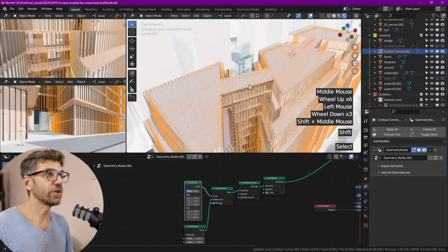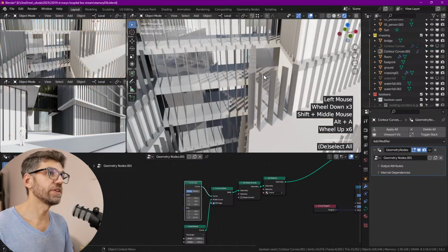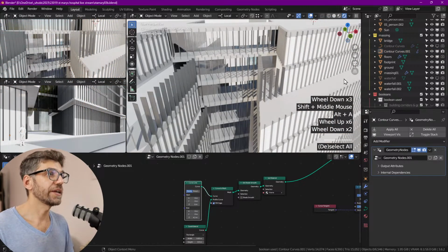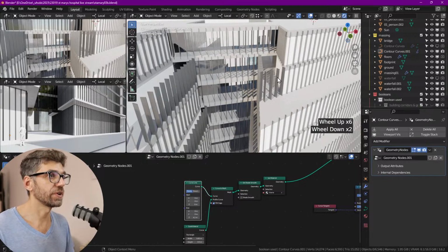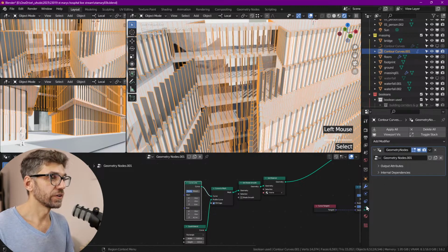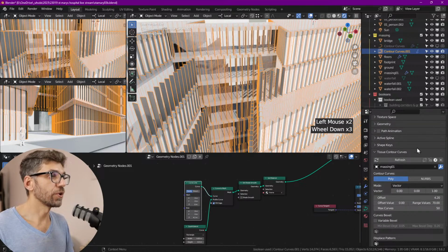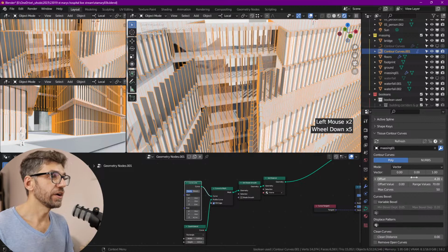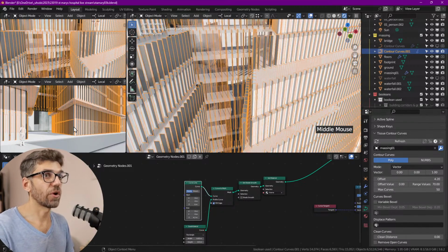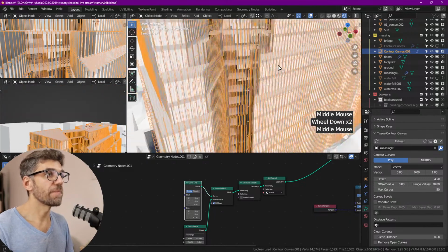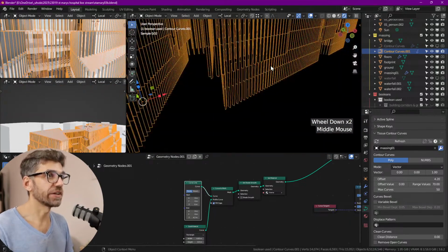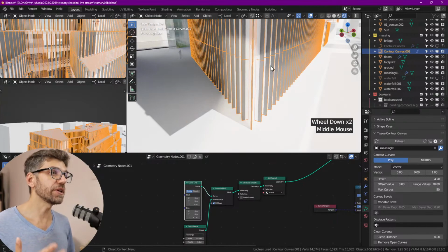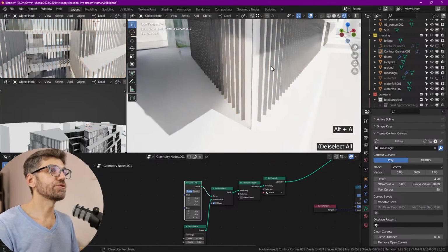And then, do you notice how every once in a while we have a couple of things that are not quite aligning? So that has to do with our contour geometry. So if we click on it, it's called contour curves, and we go to massing, and here we might want to change the offset value a little bit. In fact, on the ground floor, we might have a different kind of facade, right? So the mullions might be different. Something could be different on the ground.